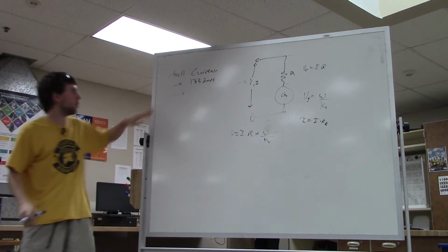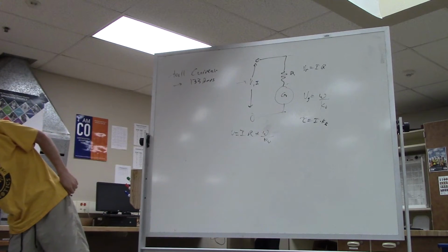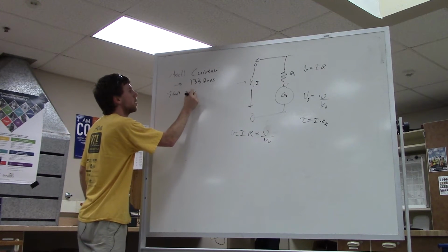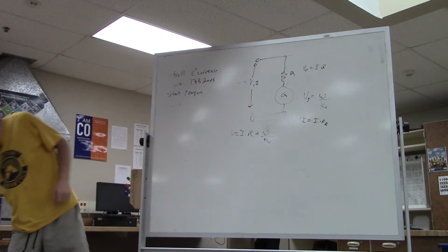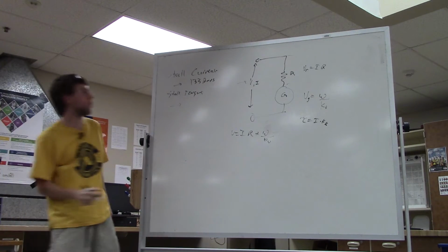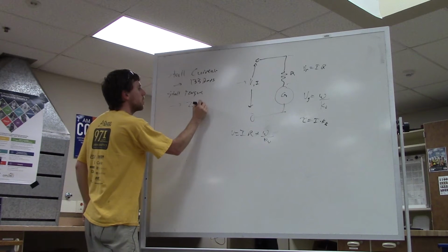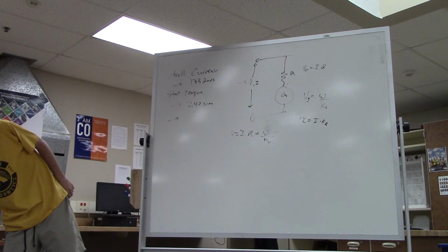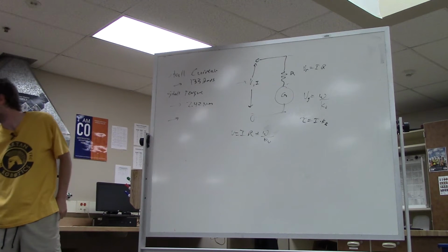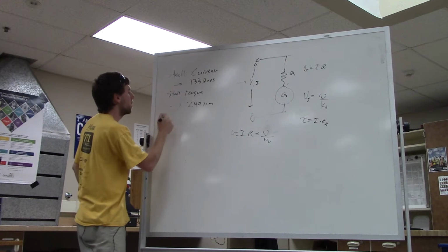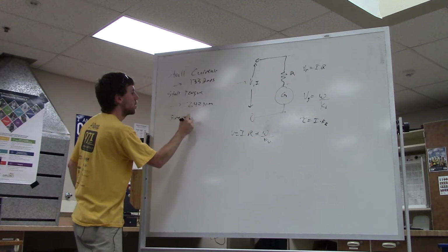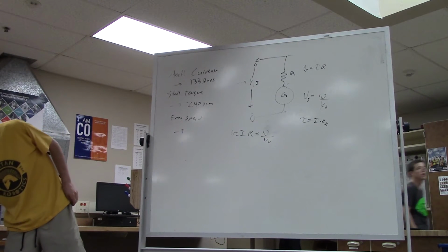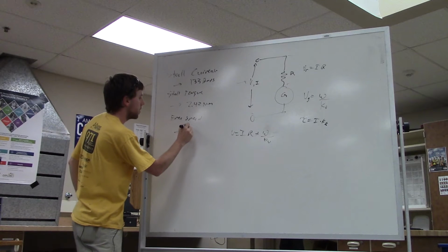And then we have the stall torque. The data sheet says that's 2.42 Newton meters. And then, is that all we need? Yep. And then the last constant that matters is the free speed. That is, with some gratuitous rounding, about 500 radians a second.